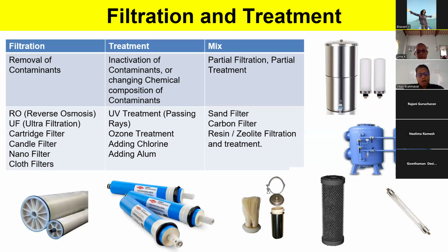Okay. What is treatment? UV is a treatment. We get different rays. UV rays of 254 nanometers kill bacteria. When UV rays of 254 nanometers pass onto the water, the bacteria's outer shell gets cracked, so it can't reproduce and can't create any negative effects. So basically you're disinfecting, which means the bacteria is not alive in the water, but it is still there in the water. If you pass the water through UV, the outer shell of the virus dies.